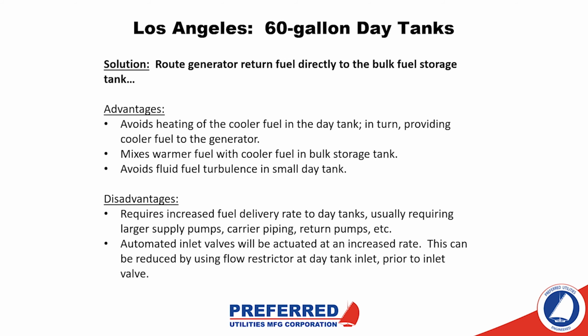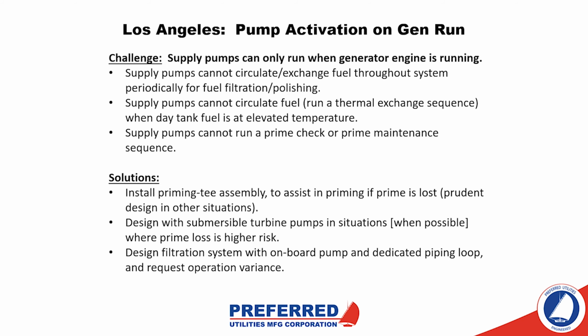So another issue that we run into in Los Angeles is the pump activation on gen run rule. And that is basically we can't run the supply pumps unless at least one generator engine is running. So what this means, if we start going through the bullet points here, is the first one: supply pumps can't circulate or exchange fuel through the system periodically for fuel filtration or polishing unless there's a generator running.